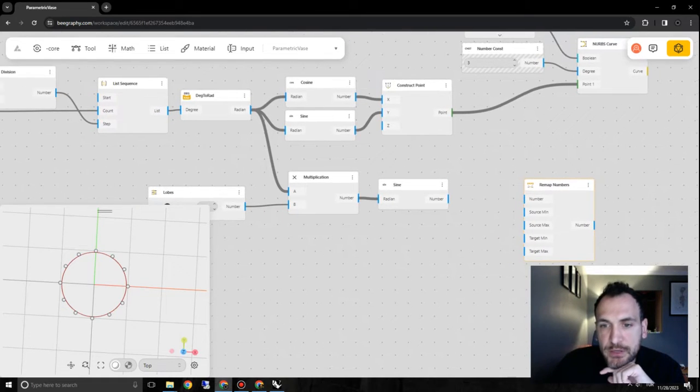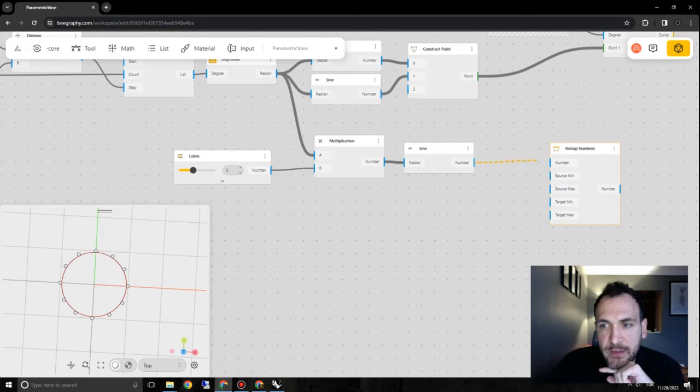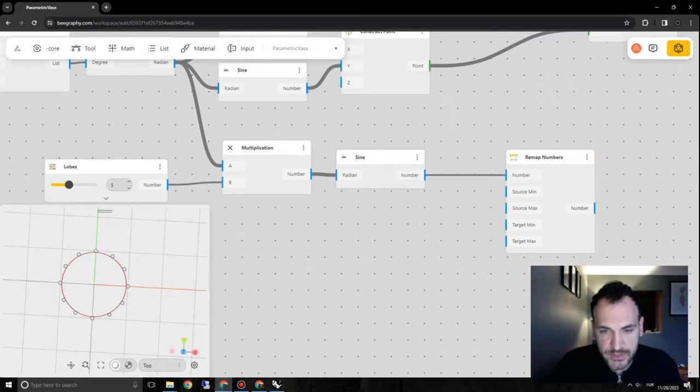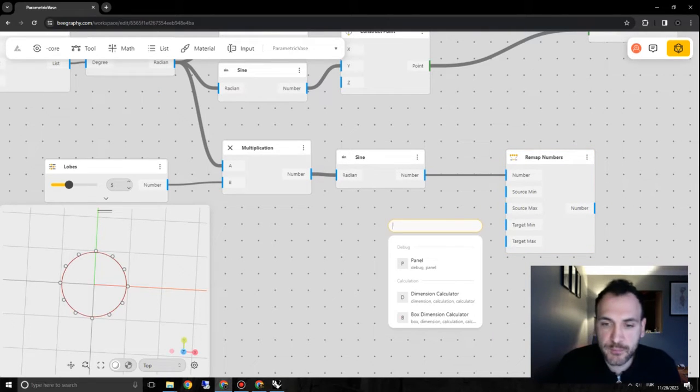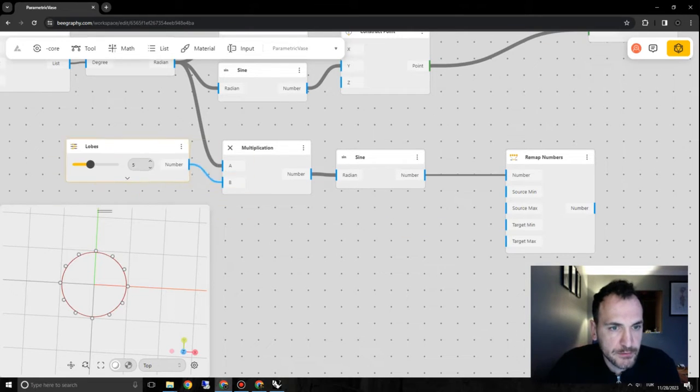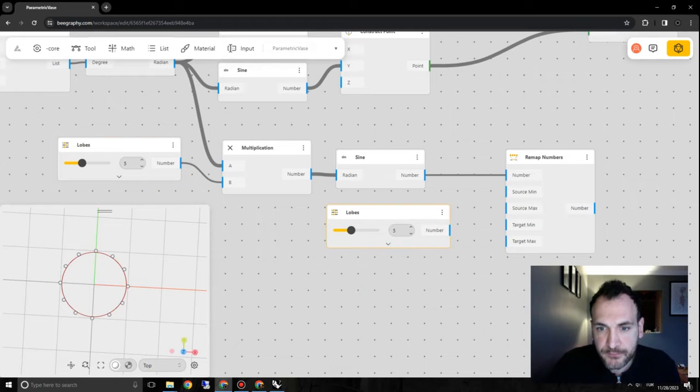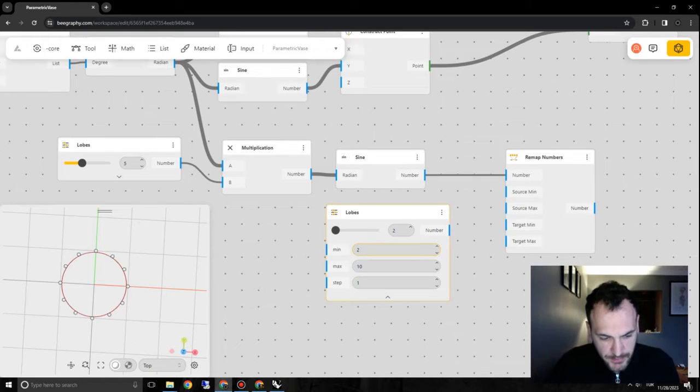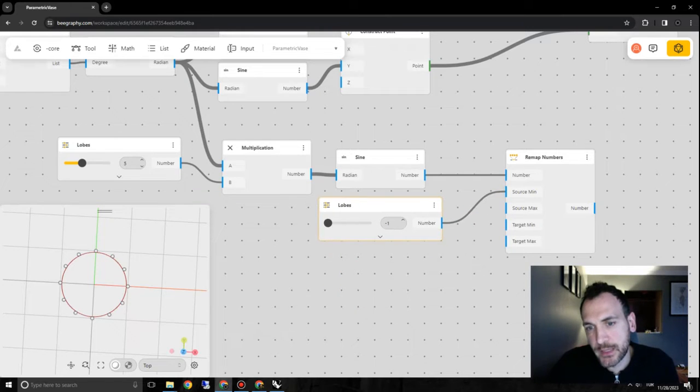Now this is similar to Grasshopper again. Now we want to remap these values that belong to a source domain that we already know, which is basically between -1 and +1. So I can create another number slider here. So we can copy paste this. Let's try entering -1. It actually could be minimum is -1, positive is 1. So this will go into -1, and our source domain is between -1 and +1.